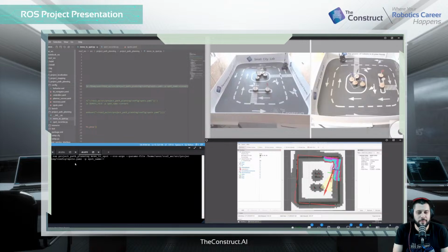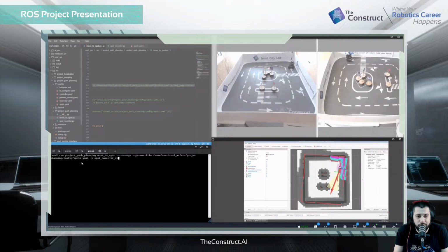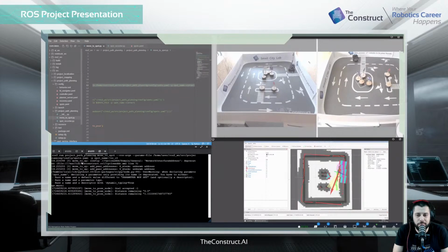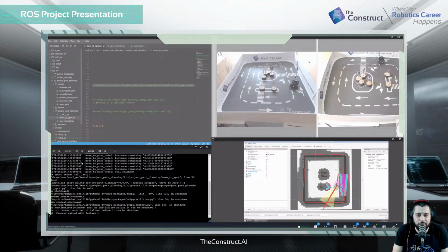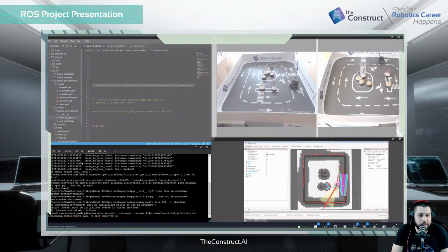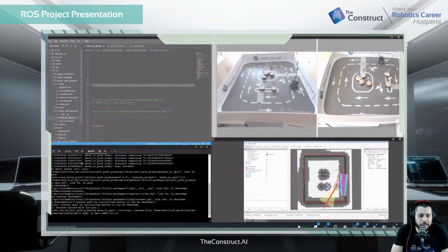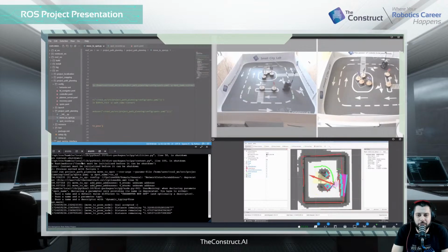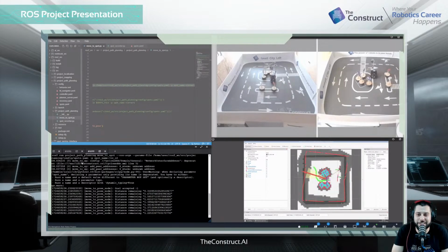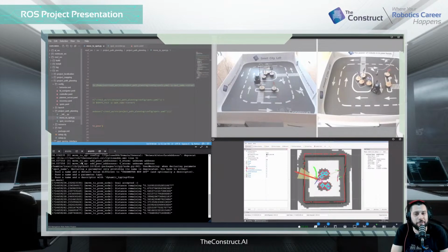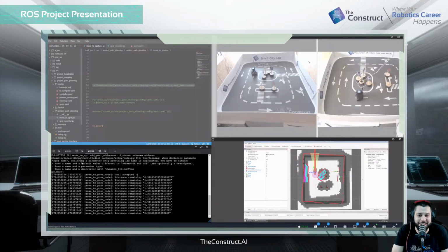So I've named these spots in a file, and then I'm calling them right now and navigating to them with the path planner, which is all inherent to this navigation course. So we got 1 point, and I figured we would do a brand new point as well for this presentation. And it's interesting because here you can see the replanning done. I saw it went around a couple of times 'cause it chose a different path. Awesome.